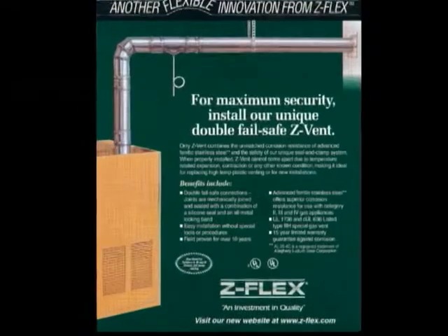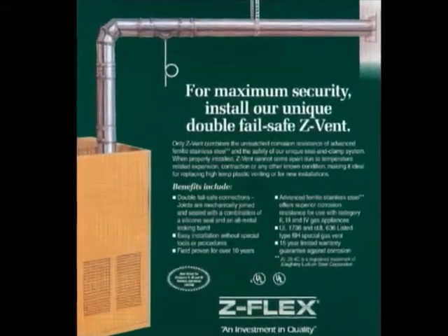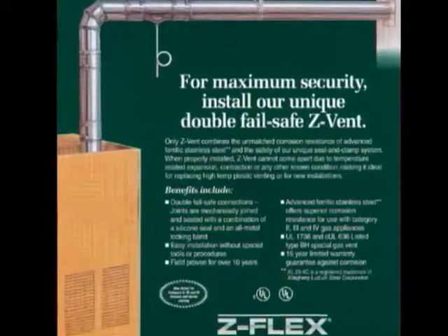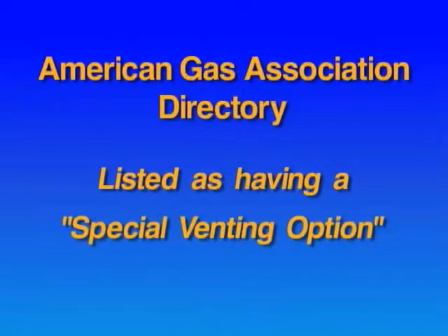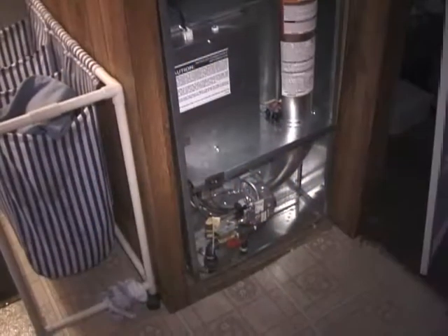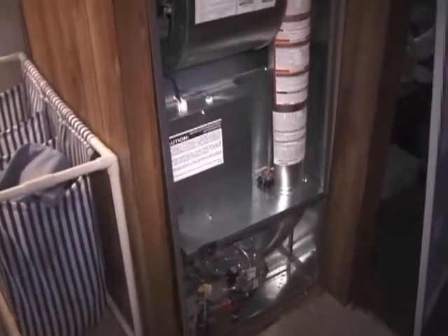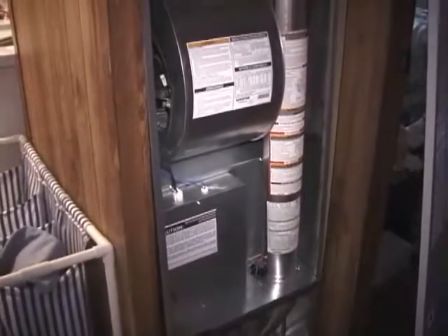This actually then converts the appliance to a Category 3 type. In these cases, the vent system must be supplied or recommended by the manufacturer of the appliance. Installation should also follow the manufacturer's instructions exactly. Category 1 appliances that have this venting option are listed in the American Gas Association directory as having a special venting option. One other particular type of Category 1 appliance is actually a sealed combustion unit.